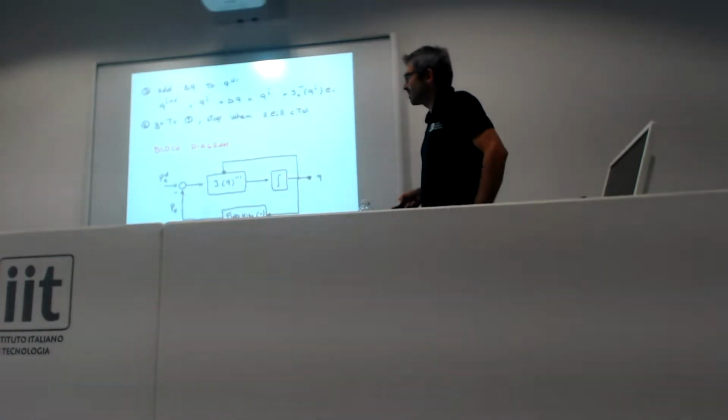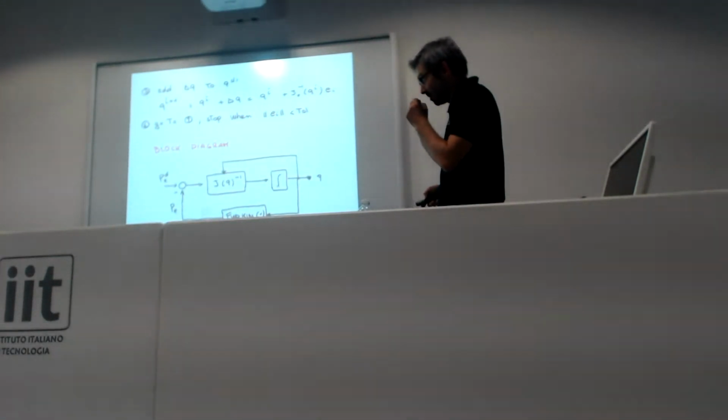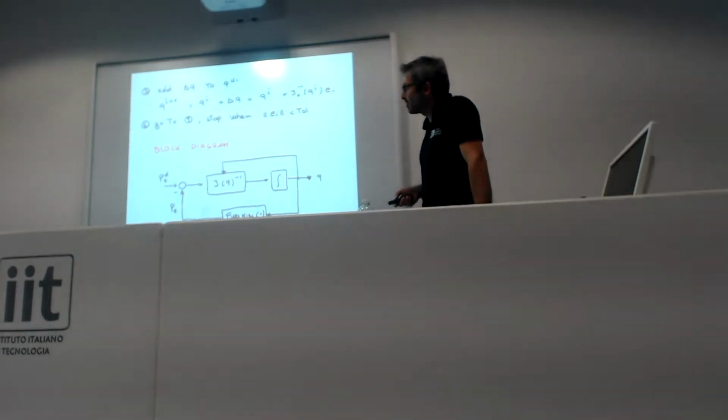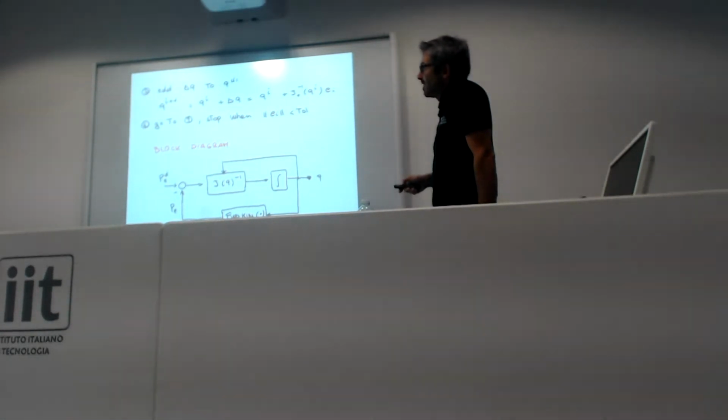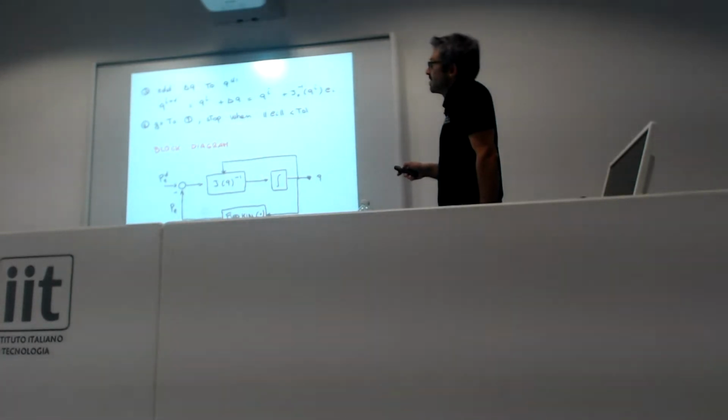This is the block diagram of this approach. We map the error at the end effector through the Jacobian into an error at the joints, and then we integrate. This is in essence the integration step, and then we compute again the new end effector position and we iterate.